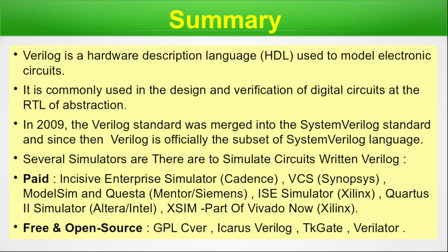Now we have a couple of names of free and open source Verilog simulators that you can start using right now. In the playlist, you will find installation and usage videos for these. One is GPL Cver, another one is Icarus Verilog. Icarus is very popular because it simulates both Verilog and SystemVerilog. Next we have TK-Gate, which is a GUI based HDL simulator, and we have Verilator. So these are a couple of names of paid and free open source Verilog simulators.